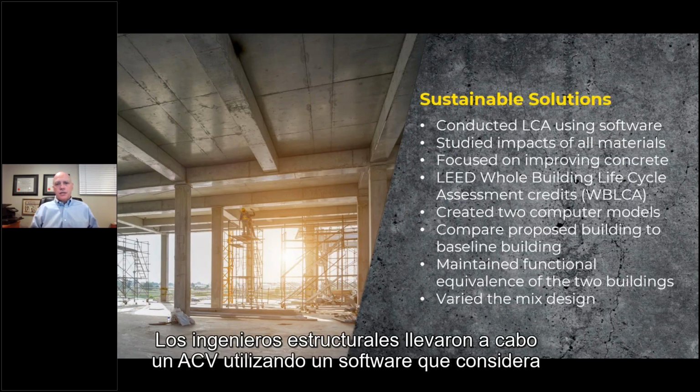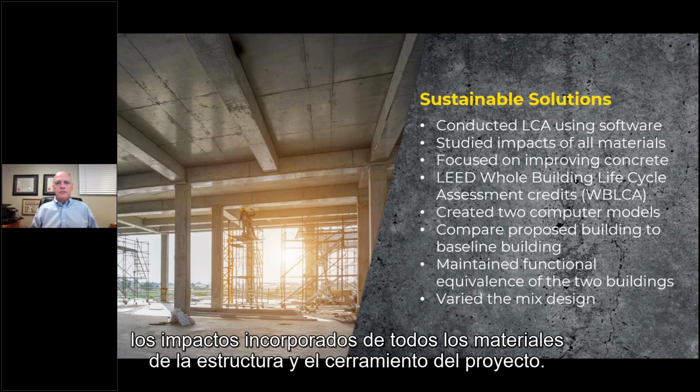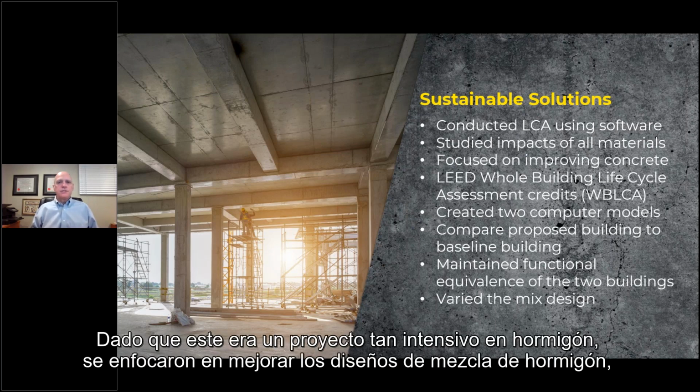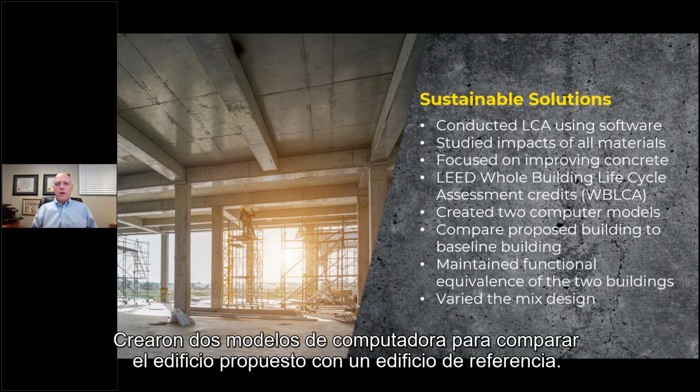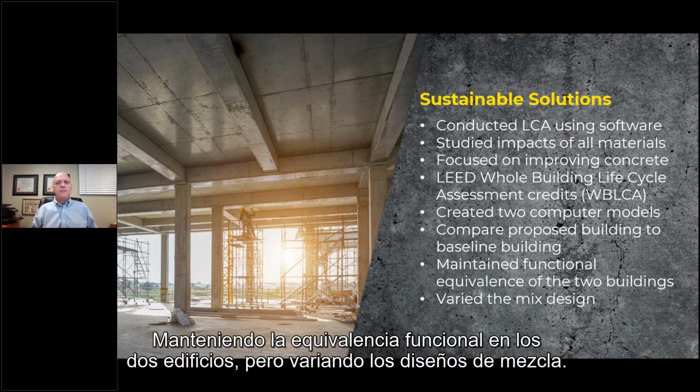Structural engineers conducted an LCA using software which considers the embodied impacts of all materials of the structure and enclosure for the project. Since this was such a concrete intensive project, they focused on improving concrete mix designs to meet the LEED whole building LCA criteria for lowering environmental impacts. They created 2 computer models to compare the proposed building to a baseline building, fully maintaining the functional equivalence of the 2 buildings, but varying the mix designs.